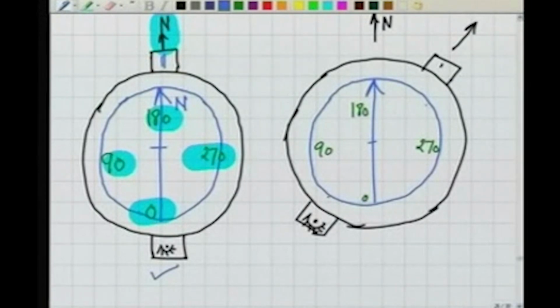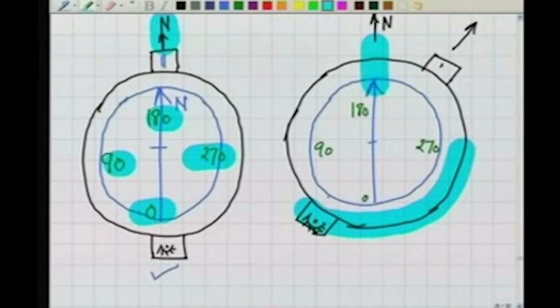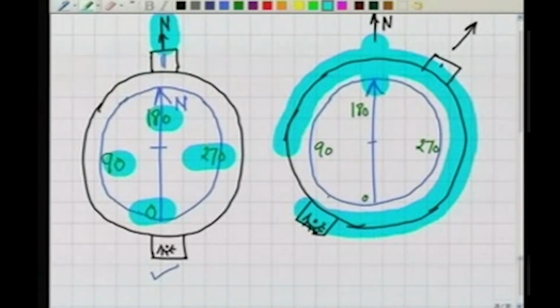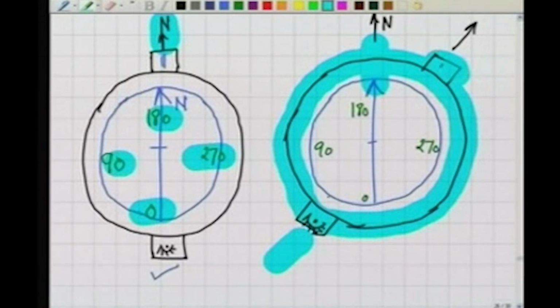So when I bisect the ranging rod at B, what happens there? This needle will stay where it was, because the needle points in the north direction. So the graduated circle will also not move. What moves? Only the body of the prismatic compass, only this black line, it moves along with the eye vane and the object vane. Now at this moment, if I look through the prism kept here, it will read the graduated circle here. So the reading in this case will be, as you can see, around 45 degrees.